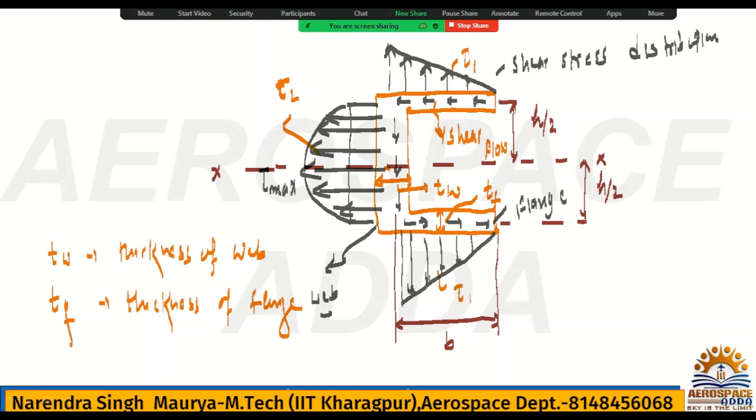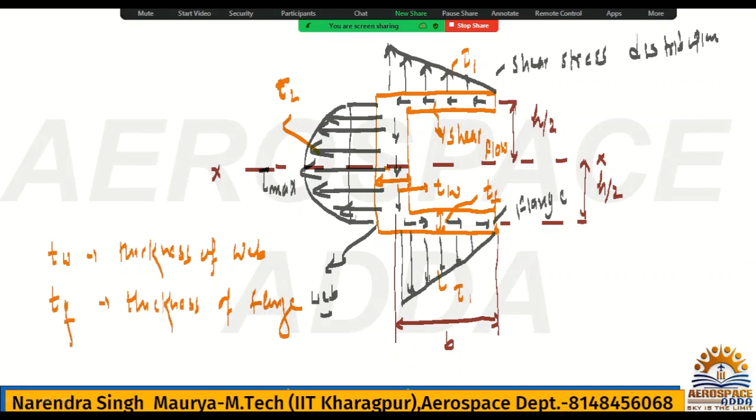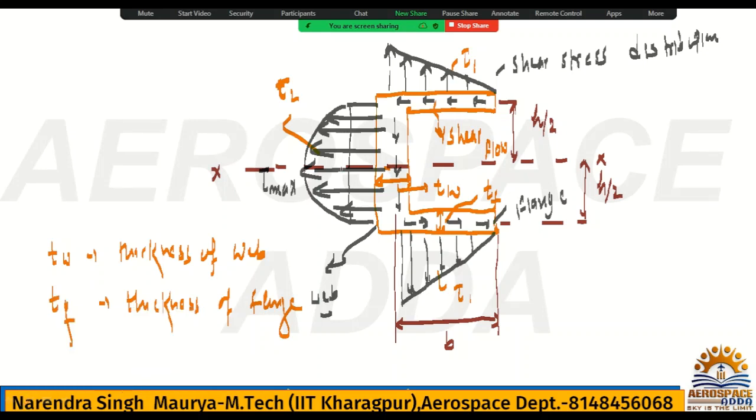So for that reason, if you check the centroid point of the shear flow, combining all three, where are you getting more shear distribution? You are getting more and more shear distribution near the web, and on the opposite side, if this is the C channel, you get less. So for that reason you will get the shear center here.